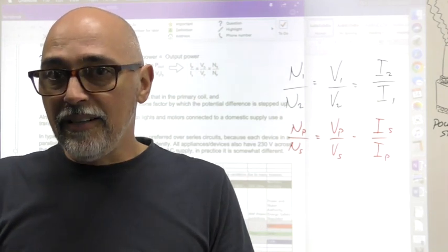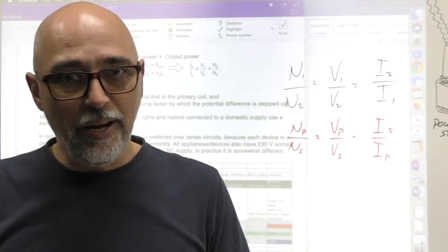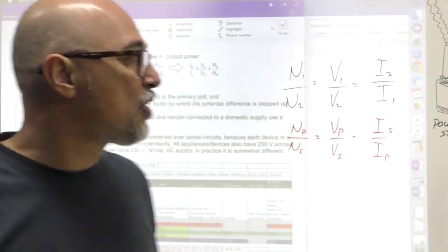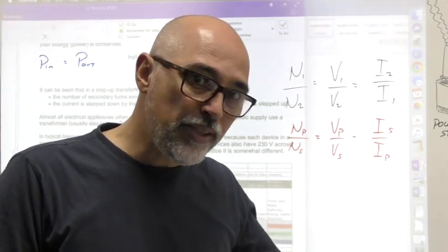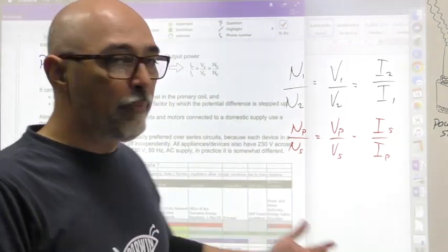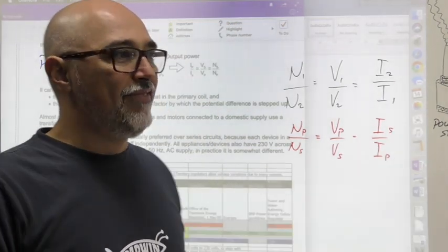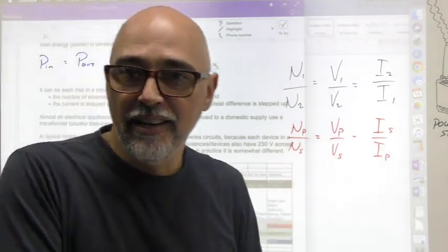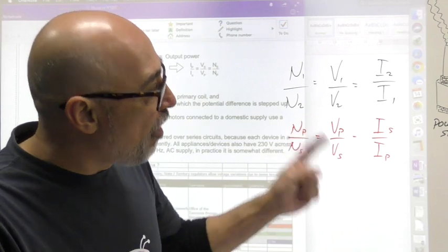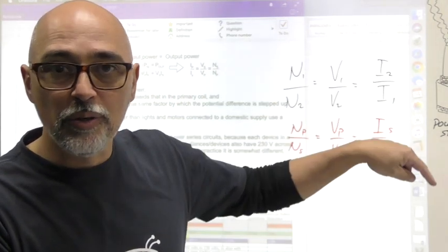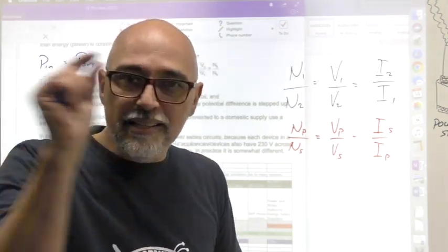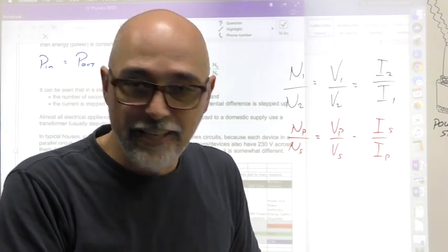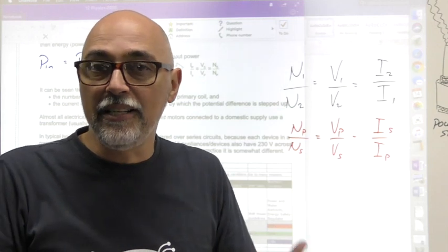In the transmission lines, you will have a loss somewhere, okay? All along those transmission lines because of their resistance. So the power put out by transformer 1 will be, say, 10,000 watts, but you might get 9,990 watts arriving at transformer 2. Why? Because the lines that transmitted that power got a little bit warm on their journey, and that's where some of that energy went.